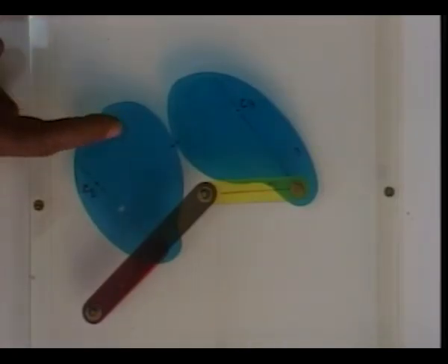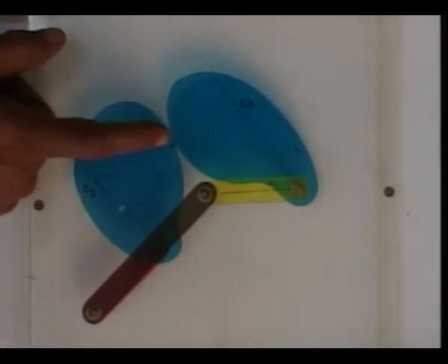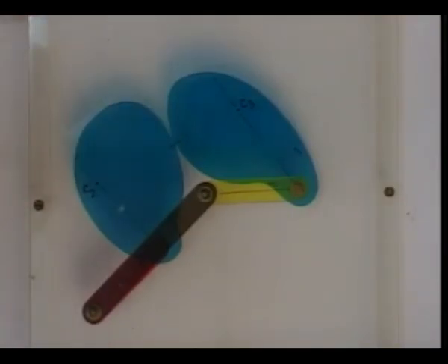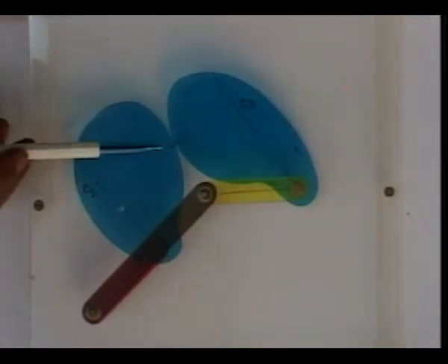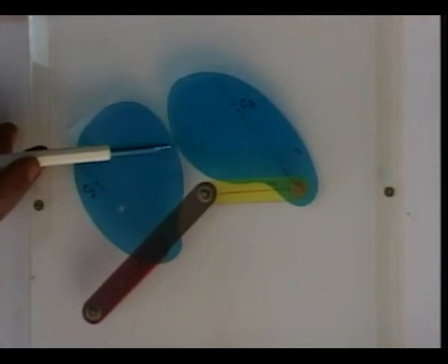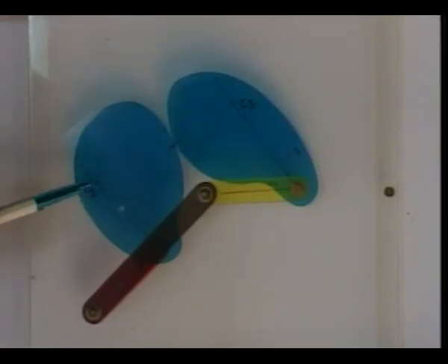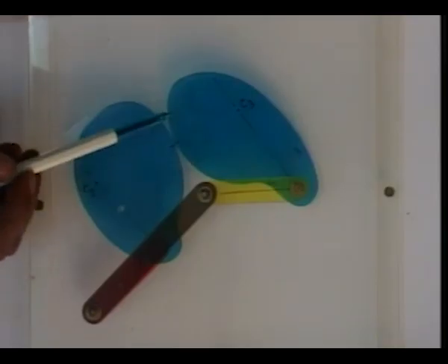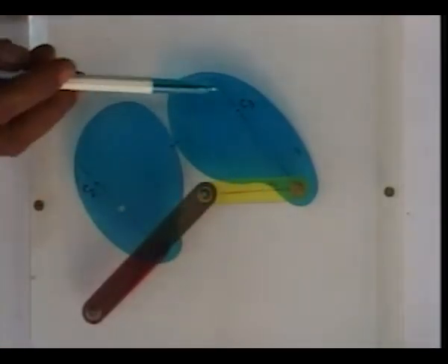Now I will show these two equivalent lower pair linkages by models. Let us consider this model where we have a higher pair mechanism, and link 2 and link 3 have a higher pair at this point. The center of curvature for body 2 at this point of contact is here at C2. Similarly, the center of curvature of this surface of body 3 is at this point C3.